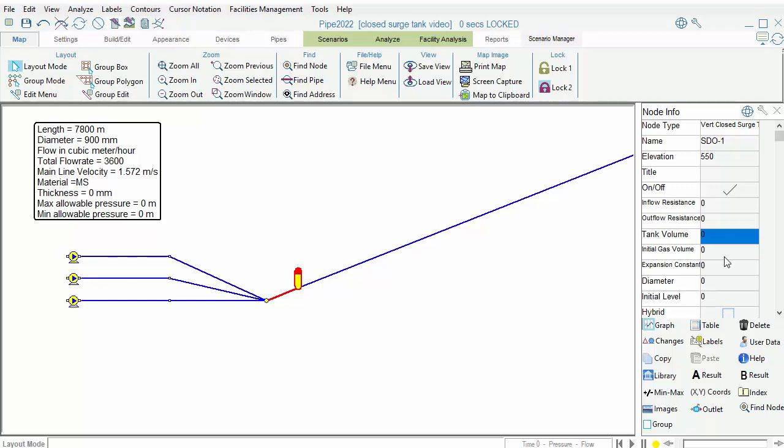But what tank volume should you start with? It is easy enough to select a volume that seems logical and simply run multiple surge analyses, trying different tank volumes iteratively. However, a rough idea of the required initial air volume can be estimated based on the initial pipeline flow and the overall length of the pipeline to other storage facilities.